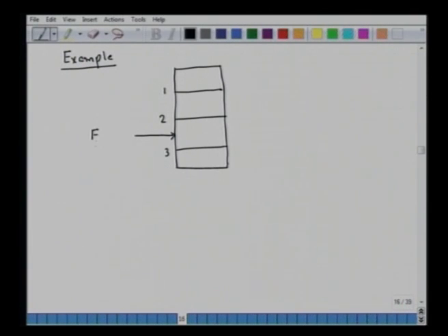Let's say the flow rate is F and the mole fraction is XF. Let's say we have an ammonia plus water system, so it's an aqueous solution. The feed composition is 0.005, and it's a saturated vapor. If you recall, when the feed is a saturated vapor, we say that q is 0. So that's your q line.